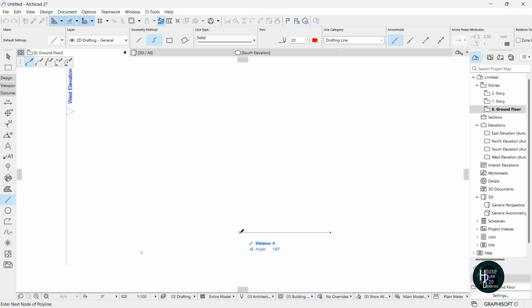I want you to make sure that you're following me the way I'm making the design. This is very, very important because I'm trying to sketch the ground floor plan design out, so that we can go ahead to do the exterior walls, then come inside and do the interior walls. So that's what I'm trying to do. Just make sure that you guys are following me and getting the right dimension. From here to here is 7244. I want to start from this side to this side here. It's very, very important you do that.